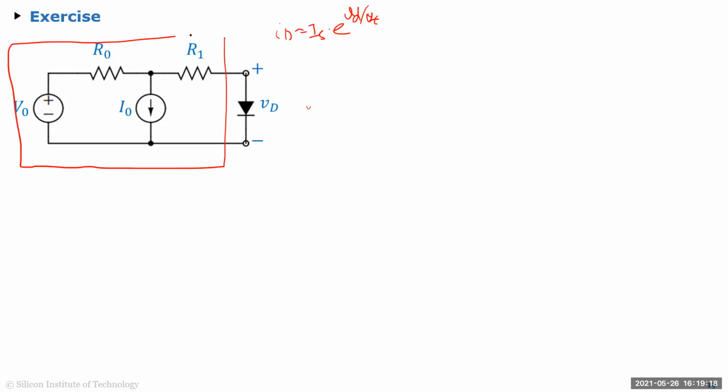that you can find the Thevenin equivalent for this, right? And then it's easy to calculate. Usually when you have a diode, you are trying to calculate the current through it because the voltage is around 0.5, 0.65 volts. For example, if this was an LED and you wanted to know if this circuit can drive the LED, or if it is going to draw too much current, the best approach is to find the Thevenin equivalent for this.